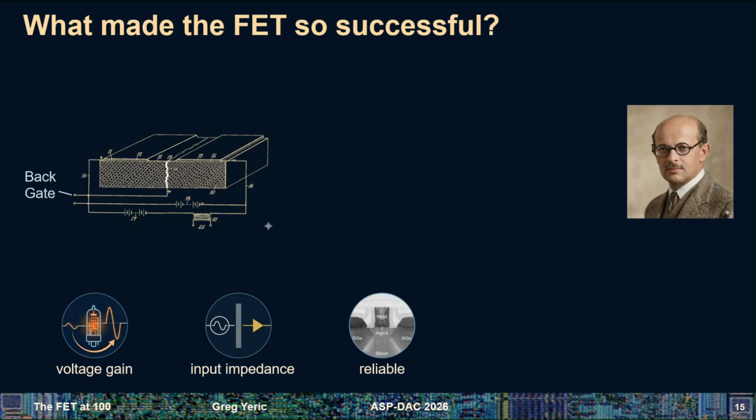It's a convenient way to make a gate, the gate signal to a semiconductor film in a lab, but gates coming from the back often lack a property called self-alignment to other parts, like the contacts of the transistor. So self-alignment of features is a major part of nanometer era process nodes, and you don't really get that when you do the backgate. So if you don't encounter that in this semester's processing class, or maybe you already did in the last semester, if the concept of self-alignment is not apparent to you, let's be sure to talk about that. You can't really divorce the processing from the device in any modern era transistor.